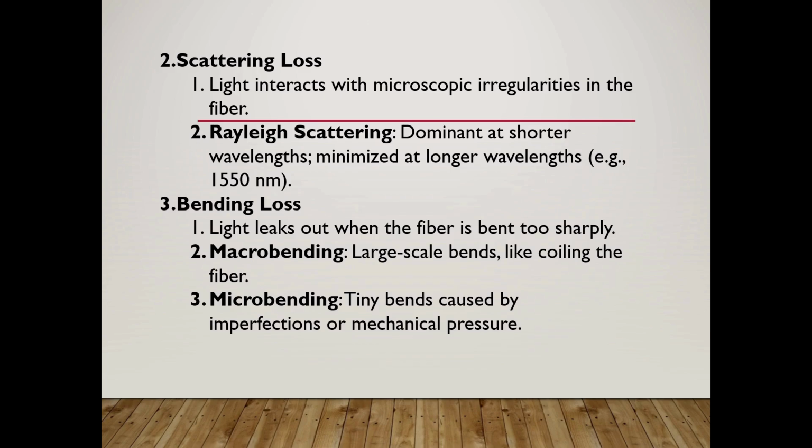Bending losses are particularly concerning because they can occur during installation or handling of the fiber. So, engineers must follow strict guidelines for minimum bend radii to prevent such losses.